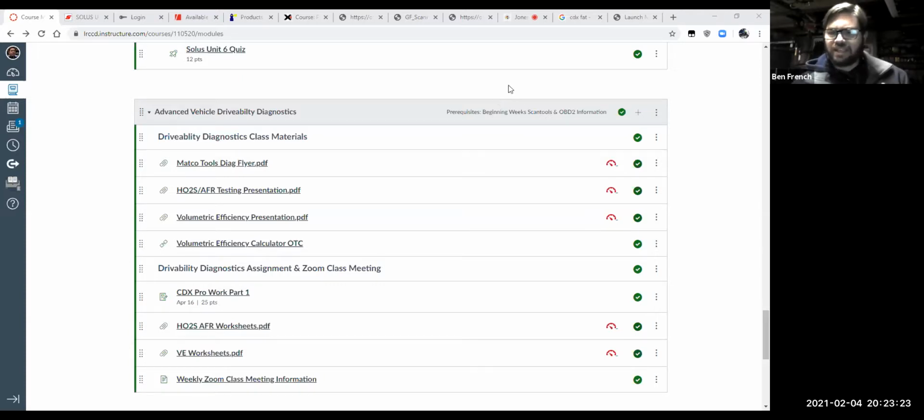Before I let you go for tonight, any last questions for me? I'm looking at the chat. I don't see anything up on the chat. So remember, no communication, try a different scan tool, right? And if you only have this little interface, go to O'Reilly's or AutoZone.